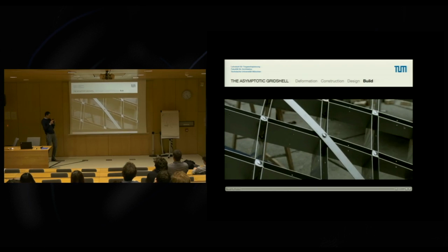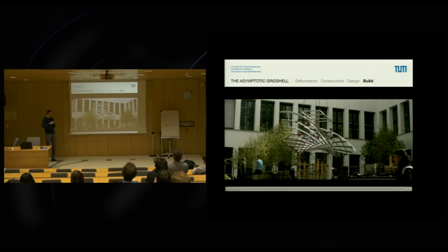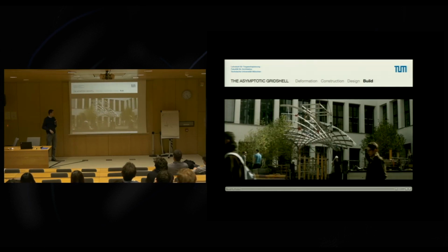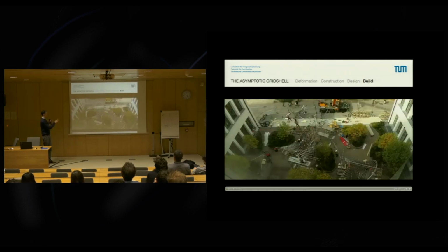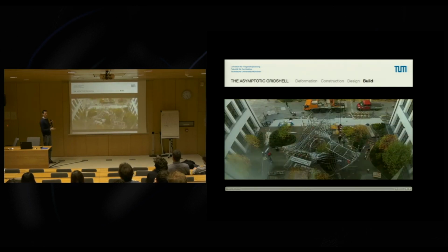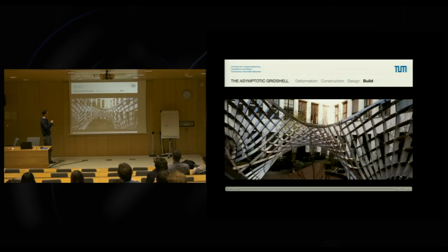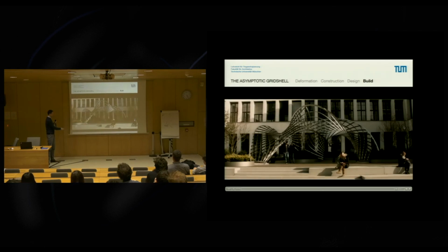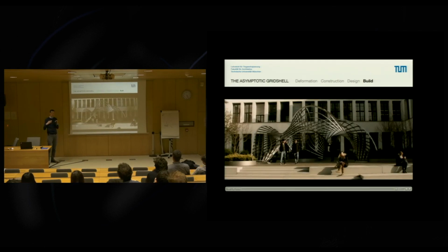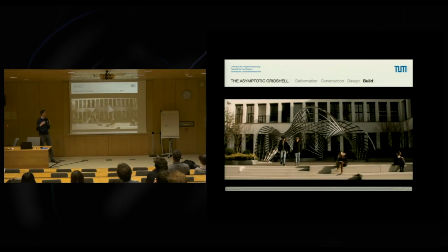And once it had reached that, we fixed the nodes tightly and added some extra edge supports. So these 9 segments were brought to site and then combined like a large 3D puzzle. They were just overlapped and bolted together. And finally, we added the diagonal bracing that would stiffen the structure and create a load-bearing grid shell.